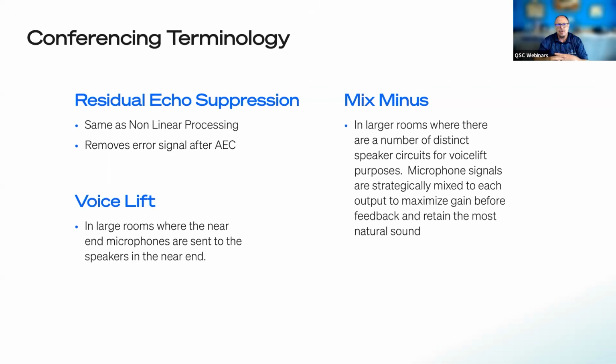And the other thing to remember, with the term voice lift, is that so many people think a microphone's not working if it doesn't sound like Sunday at the Monster Truck Rally. It doesn't need to echo. A perfect voice lift is when the person speaking into the mic doesn't realize that it's being lifted in the back of the room, yet they don't have to speak loud in order for the people in the back to be able to hear naturally. So a lot of things come into play with this. You've got to set delay right, and the amount of that, but that's just some terminology on what we're doing, and we'll go through it.